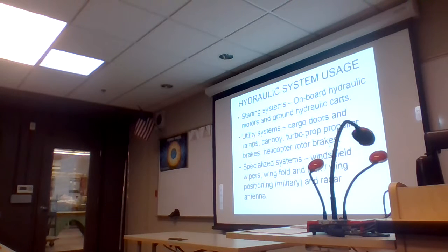Some specialized systems, some windshield wipers are hydraulic in aircraft. A lot of the Grumman military aircraft have hydraulic windshield wipers. A lot of the Sikorsky do too, the H-60 does. Wing fold on some aircraft, like the F-14, some of the others that are carrier-borne airplanes have wing fold capability. And radar antenna. In order to cause the sweep on the radar antenna, sometimes the antenna itself is movable by a hydraulic motor.